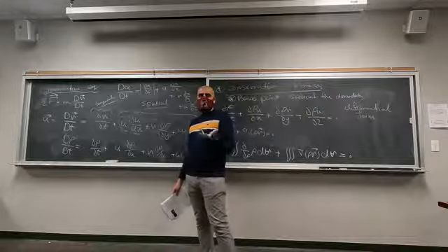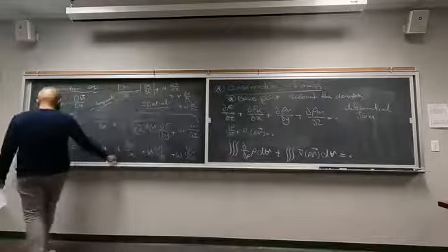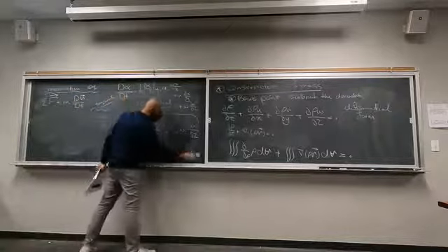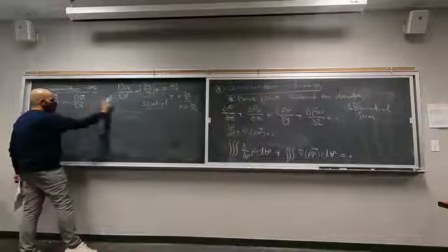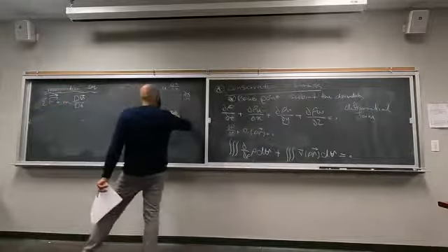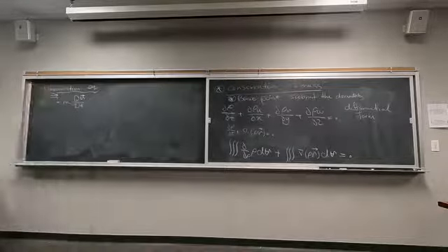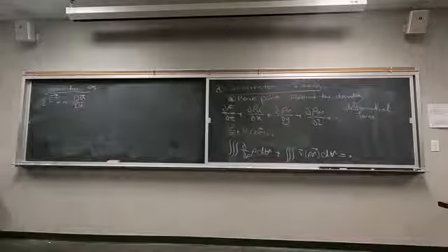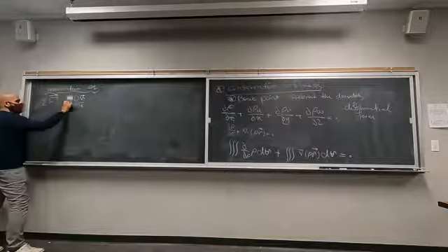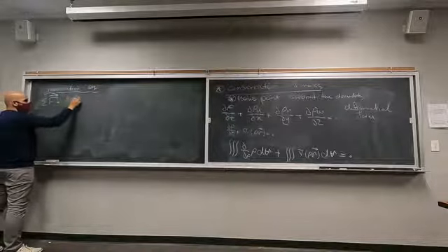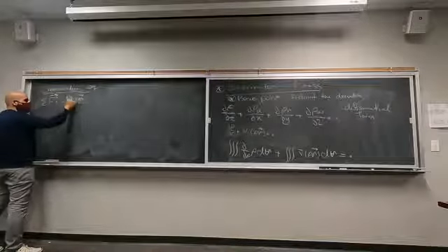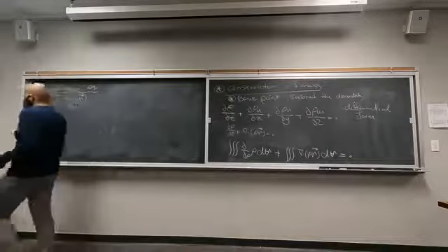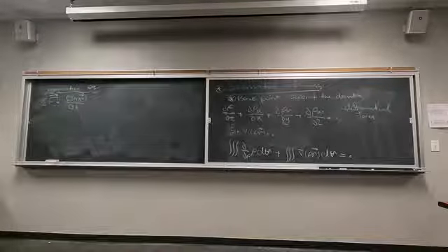But does this make sense at all? Okay. So we understand the total derivative. We understand the total derivative for acceleration. And let's go back to the momentum equation. The idea was, momentum equation is based on Newton's second law. Let's talk about this left-hand side of the momentum equation first. M, total derivative of V with respect to t. This is actually, to be a little more accurate, we have to do this, total derivative of mV. mV is the momentum, right? The change in momentum over time is equal to sigma F. That is the real representation of Newton's second law. That's the most accurate, or most general, representation of Newton's second law.